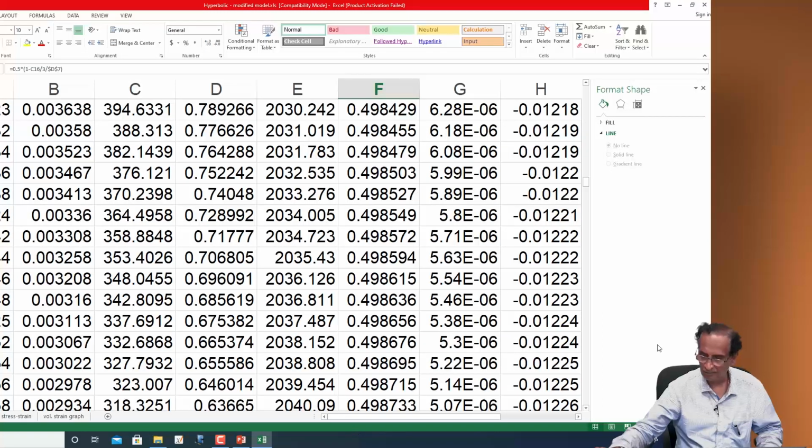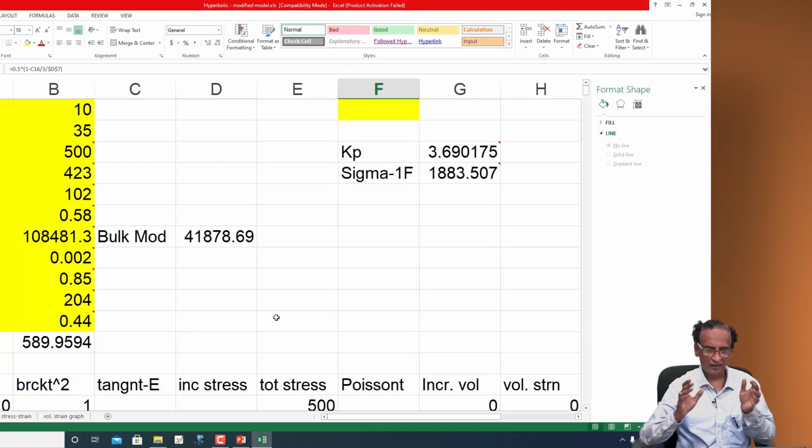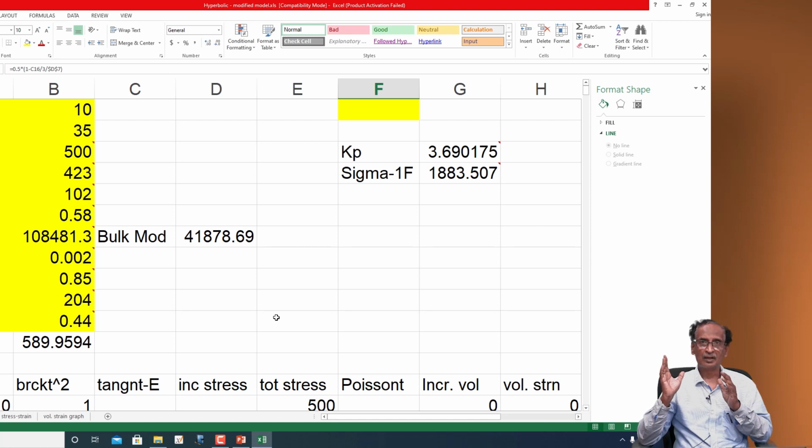And so, because we are representing the constitutive matrix in terms of a tangent Young's modulus that is a function of the shear stresses, and a bulk modulus that is not a function of the shear stresses, there is no failure term in the bulk modulus.